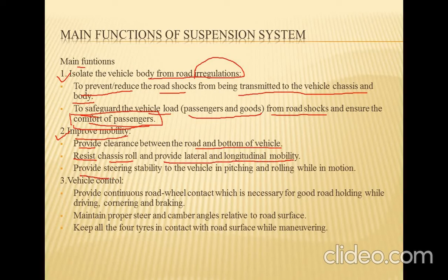Then it is to resist chassis roll, and it provides lateral and longitudinal mobility. It provides steering stability to vehicle in pitching and rolling while in motion. We'll discuss pitching and rolling in the next slide.